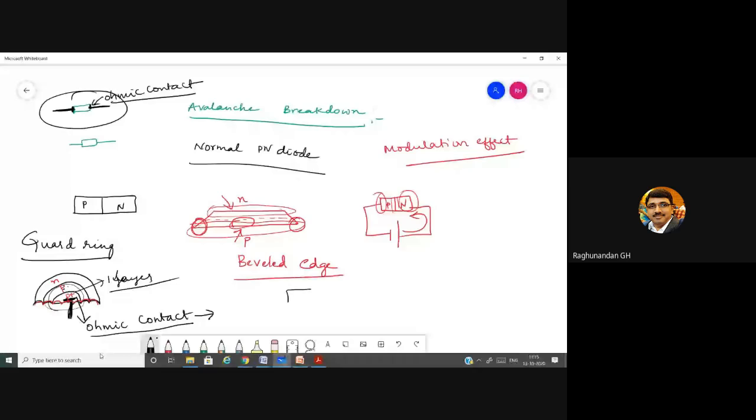These are known as the guard rings. Guard rings are going to isolate the junction where the avalanche breakdown occurs. Because of this kind of shape, a ring like structure instead of a flat structure, it is going to overcome the avalanche breakdown for a shorter duration, such that at least some portion of the depletion layer will be retained for some amount of time.